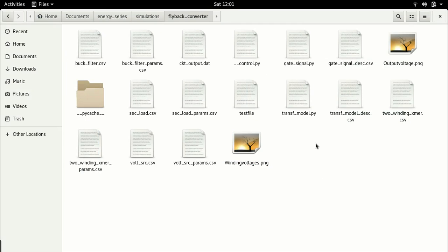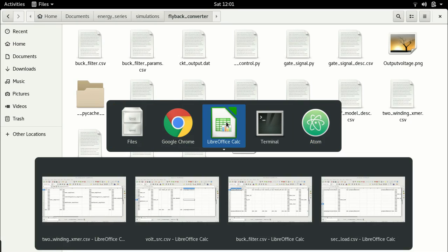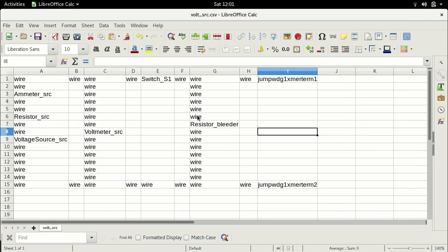Now, question is, why is this topology not still what we want, right? The reason, simply speaking, is we cannot just connect a resistor like this, right? We've connected a bleeder resistor, and the reason for this bleeder resistor was that the magnetic energy in the transformer, and therefore the induced EMF that is produced when the switch is turned off, must have a path to flow. Alright, and this bleeder resistance is the path. But a resistance like this is not at all recommended because this decreases the efficiency of the system. Right? And that is the reason why this topology is not at all acceptable.